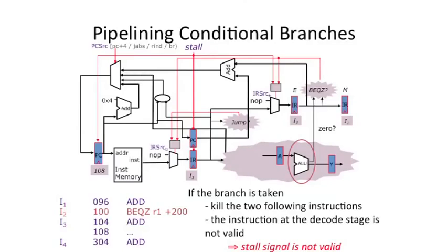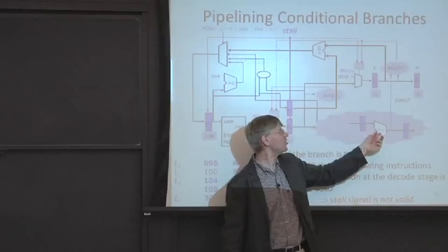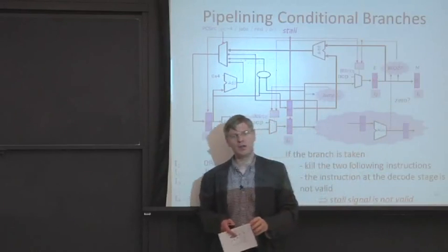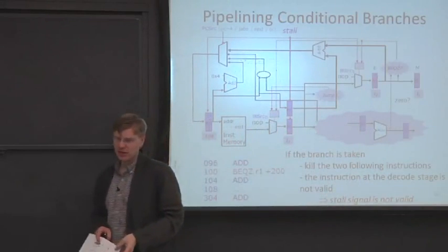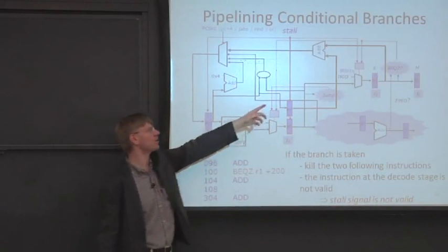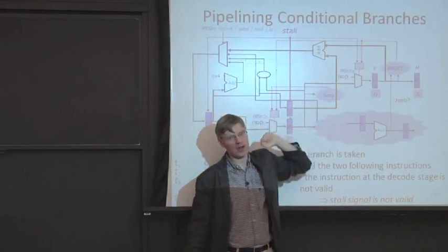And the other thing is we can't reuse this ALU necessarily to do that. You could potentially reuse this ALU if you were microcoding your design. But unfortunately, we need this ALU to do the branch comparison. So we need to add another adder here to come up with the target of our branch.